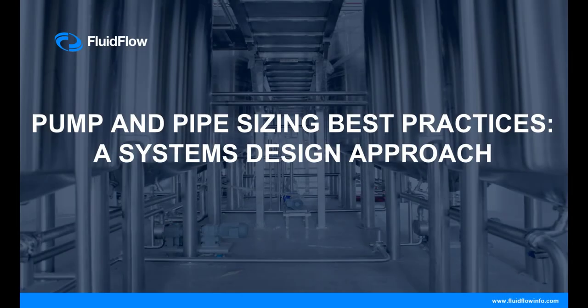In this video, we'll look at pump and pipe sizing best practices using a systems design approach. A systems design approach means looking at the entire hydraulic system as one connected network, not sizing each component in isolation. That's important because the pump, pipework, fittings, valves, elevation changes, heat transfer, and fluid properties all interact. Change one part, and you affect the flow rate, pump duty, pressure losses, temperature profile, and even whether the fluid stays safely in the liquid phase.